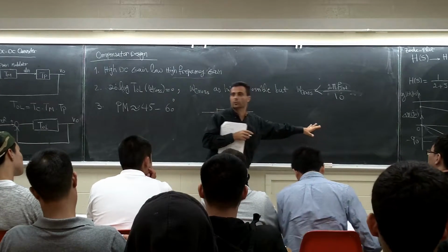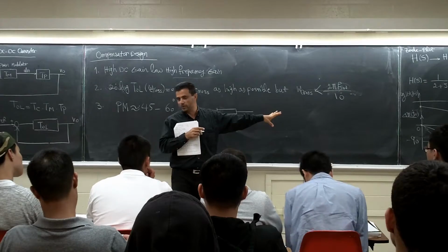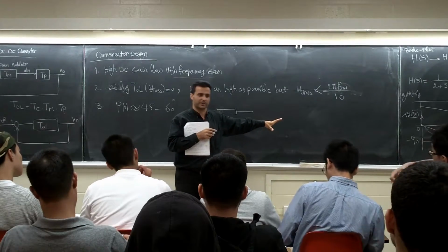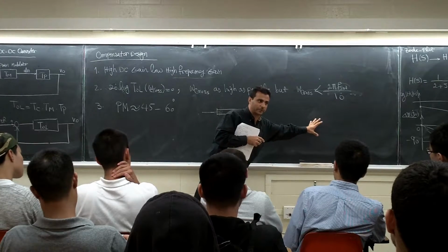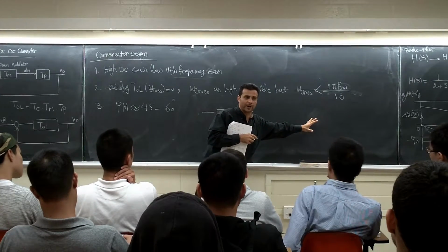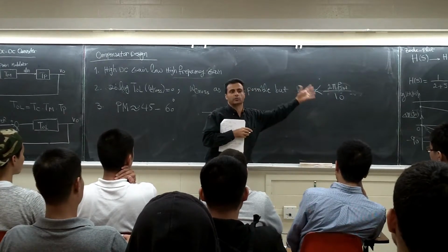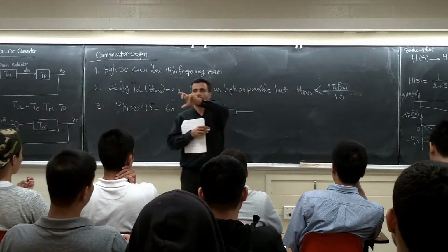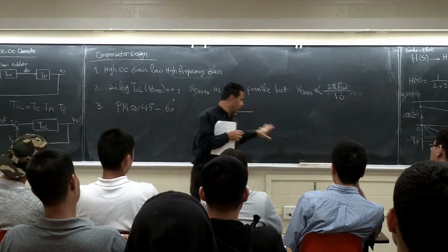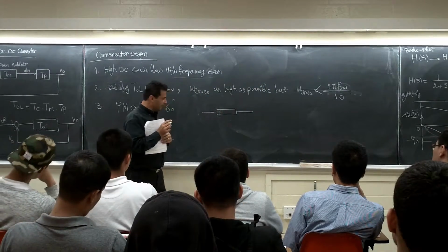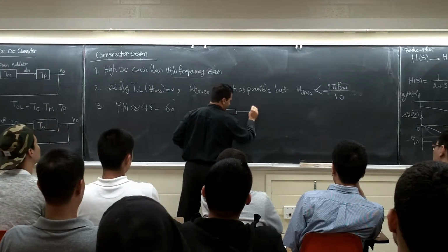That's like a PI controller. I told you the inverter. The PI controller can easily be built inside the DSP, right? You don't have to build an RC circuit for the PI. If you go back 20, 25, 30 years, they used to do that. They would find an analog circuit that works like a PI. But if we have a circuit like this.